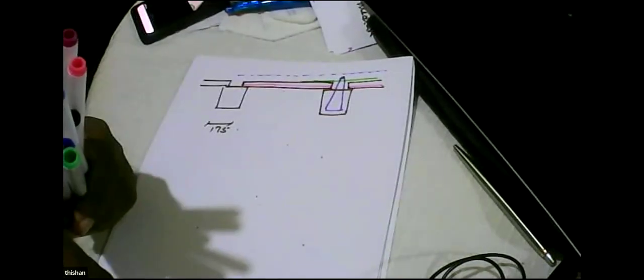Now somebody might argue, this is the top surface, so how are we going to lock it? So we thought, okay, let's have this triangular shaped reinforcement. We can put an 8 millimeter bar or a 10 millimeter bar. But when you do this, you will find that this reinforcement is having a lot of cover. Then what we thought was, let's have this reinforcement, and let's have a reinforcement at this level to lock it. And the continued reinforcement goes above it, so it will act as a top reinforcement.